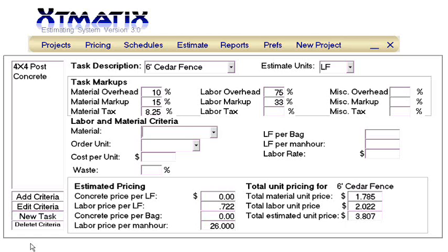The next material will be rails. With posts at 6-foot centers, we will use 2x4 rails that are 12 foot in length. This will make 2 rails with no large amount of waste per board. We can click each from the list and then enter the price per board. We will use a small waste factor, 3%.